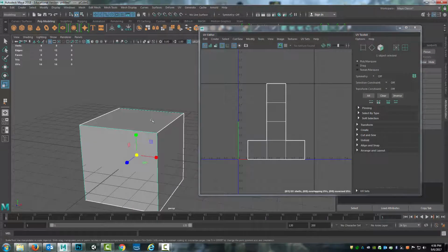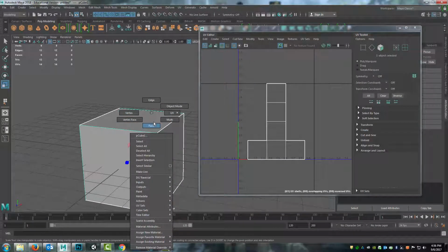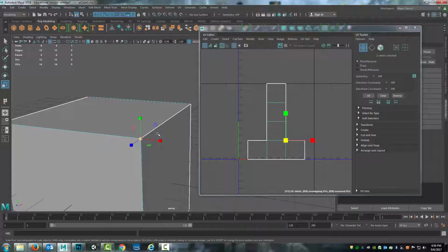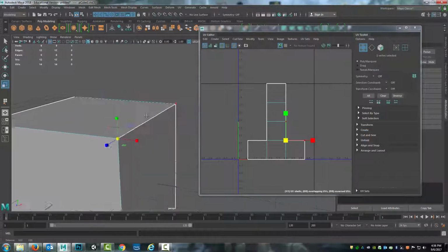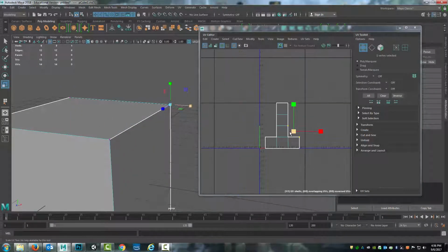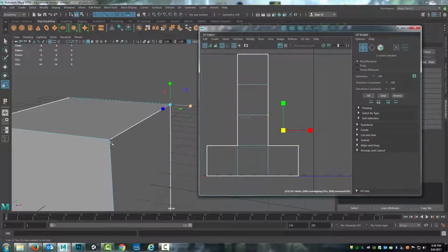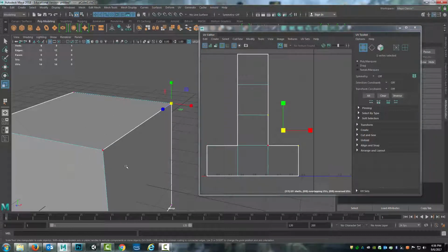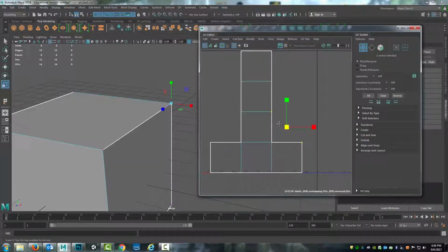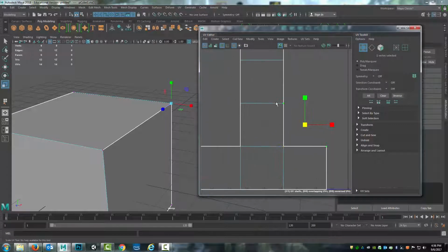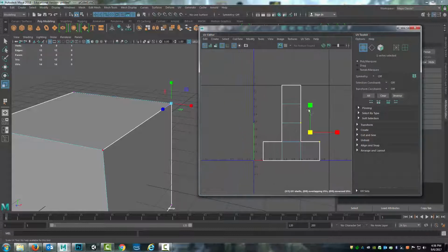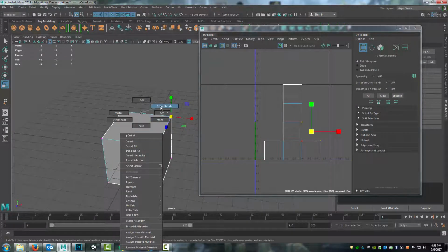So if you notice, in the model we've worked with vertex, edge, and face as components. So vertex is the point. Now that correlates also to UVs. The UV is the individual point that the vertex is made of. So in this case, there are three faces that are connecting with this vertex right here at this corner, which means there are actually three separate UVs that are being used here. So there's the one for this face, the one for this face, which currently they're being shared, and the one down here. And each primitive has its default UV layout.